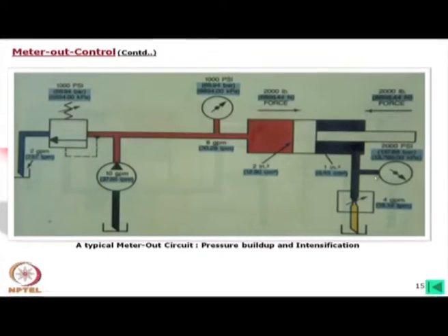So, what will happen in normal course when the drill is moving? If you have operated a drill, if the material is good and the drill is properly sharpened, you may not apply much force. But whenever, due to some reason, you have given more feed by hand, you will feel that it needs more force.